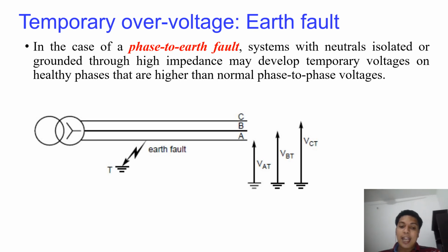Definitely a high current is going to flow through this phase A, right? Whenever you have a high current flowing through this, I think you know about mutual induction, right? So what is the total voltage in this B phase? V will be equal to E plus L di by dt plus M into dI dash by